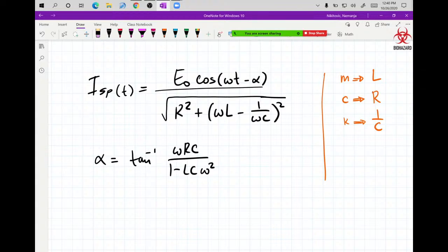But if you put in solar panels and you want to integrate that into a home grid, you can't just connect the wires and be done. Because the electricity provided by the panels and the electricity provided by the grid have to be in phase. Otherwise, they can cancel each other out.